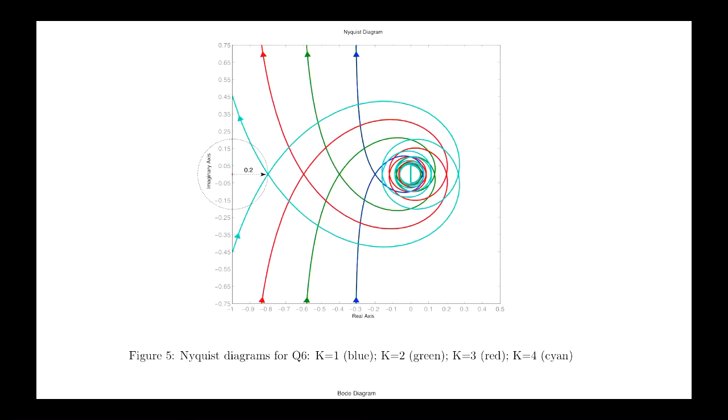As it's expanding out, the Nyquist plot is getting closer and closer to the critical point -1. So as we increase k, you would expect a bigger maximum peak in the sensitivity function. This question says to make sure that the sensitivity peak is less than 5. So I've got to draw a circle of radius 0.2, 1 on 5, because the little vector from -1 to any point on the Nyquist plot is the vector 1 plus lambda, and s is 1 on 1 plus lambda.